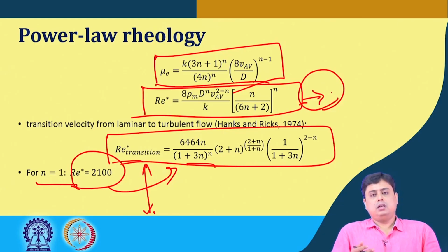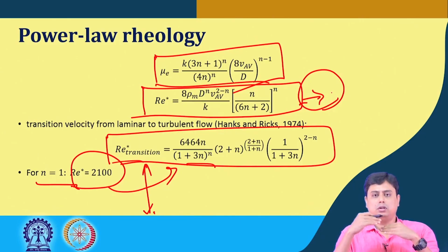So this is the calculation procedure you should typically follow when the calculation of pressure drop is involved through friction factor, because that calculation involves multiple steps. One is that you have to find suitable expressions for the friction factor. We have to get a chart. If that is available, there are two regimes, the laminar and the turbulent regime.